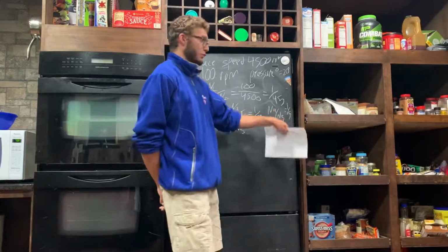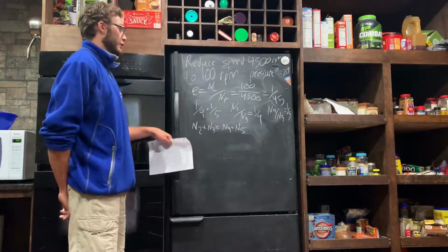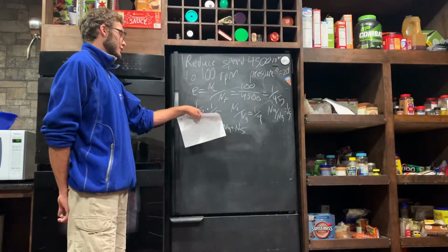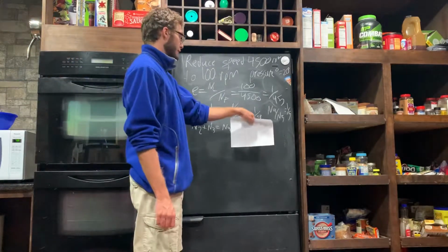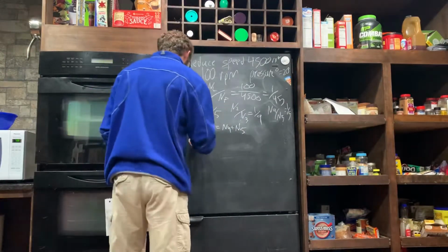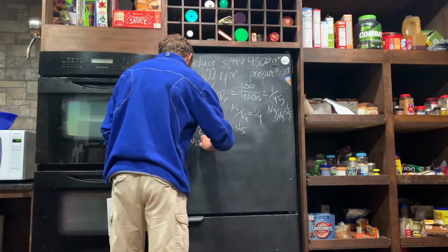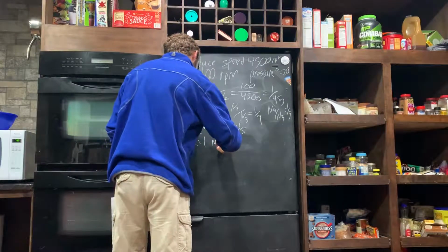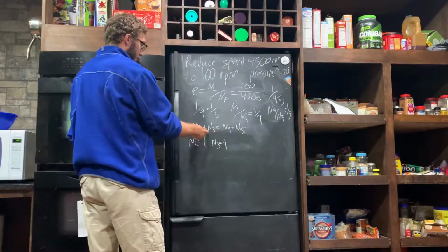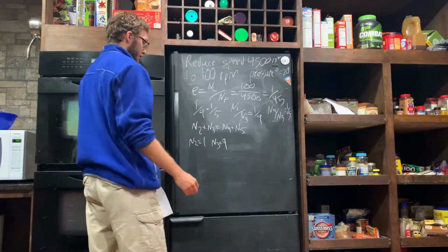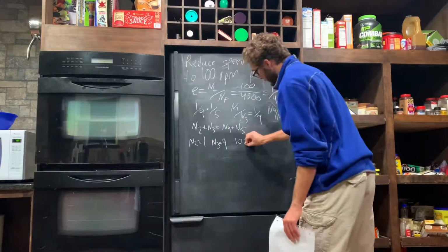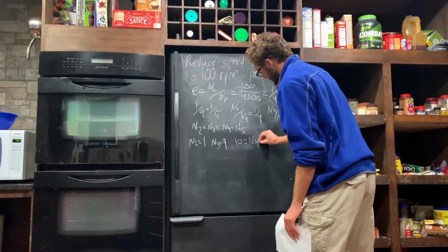We have 3 equations and 4 unknowns, but we can plug in something that fits the ratio for one side. Since we have 1/9, why not just use 1 and 9? So N2 equals 1, N3 equals 9. Plugging that back into the shaft equation, we get 10 equals N4 plus N5.